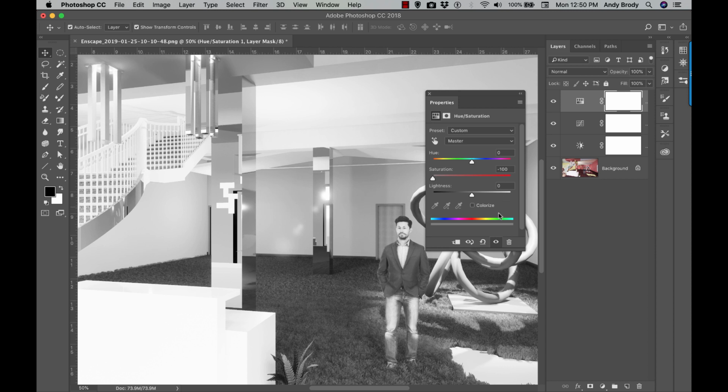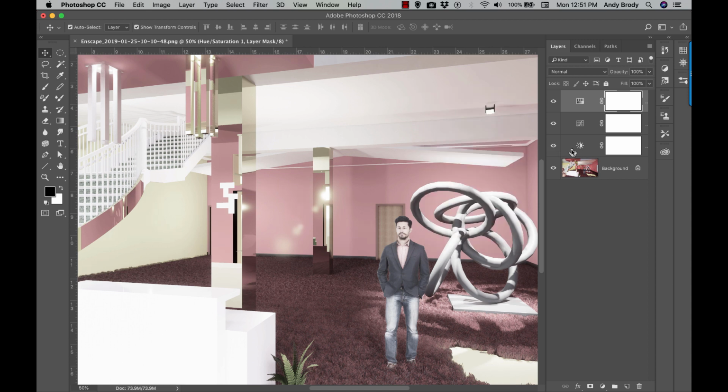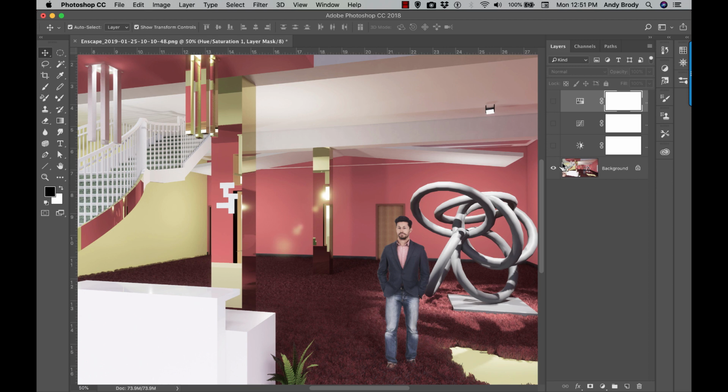I find that it really helps you talk about the kind of space and the drawing composition without being distracted by all of those materials. But even toning it down just a little bit is a good way to do it. And what's really terrific about these adjustment layers is they are non-destructive. I can just turn them off and I'm back at my original image, or I can turn one or another of them on just to kind of compare the results.